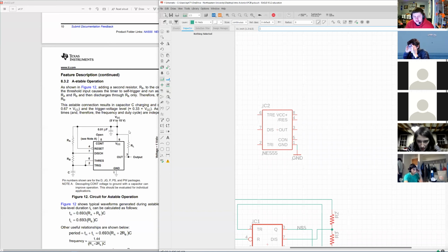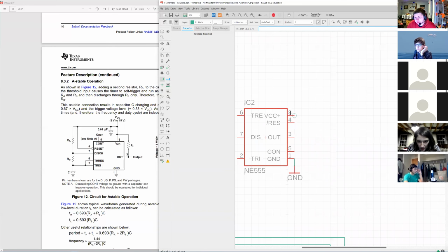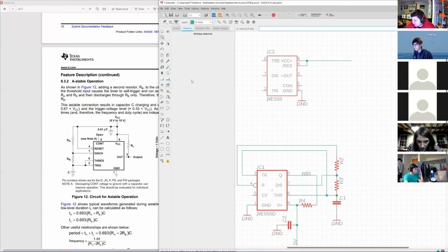How do you change the text on the labels? So Molly, I had a bit of an issue with that. What I ended up doing was if you go to info mode, so the eye with the circle, and then click on the little plus sign next to the text, you'll see a name field, and that's where you can edit it. I'm switching symbols, if you didn't notice.